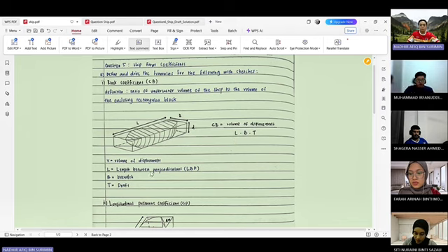Okay, next, for the big question, a ship displacing 9,000 tons has the following. For the first lot, 150 tons at 5.8 meters and 600 tons at 3.4 meters: 150 times 5.8 plus 600 times 3.4.